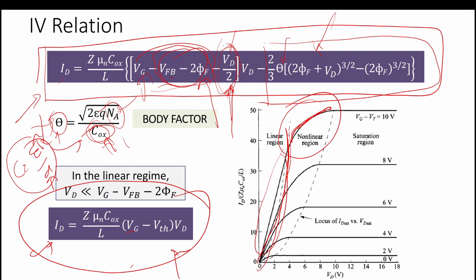And as we further increase V_D, there will be a channel pinch off. Whatever voltage we apply, as we increase V_D, there won't be any rise in the current.